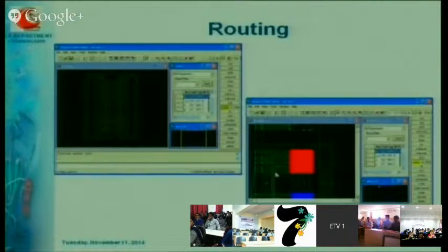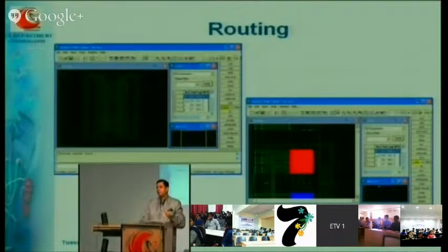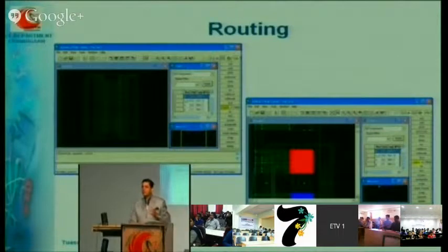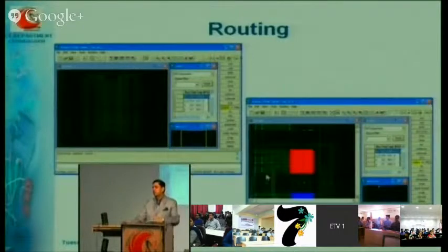Earlier you just had the information about the rat's nest, meaning information about different connections in the form of straight lines, but here these are your different routed tracks, your final detailed routing, and this is the part where your circuit is routed. So in this manner, once your logic optimization is done, the next part is your floor planning.